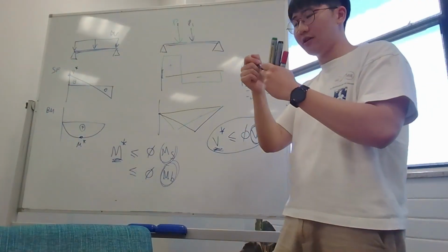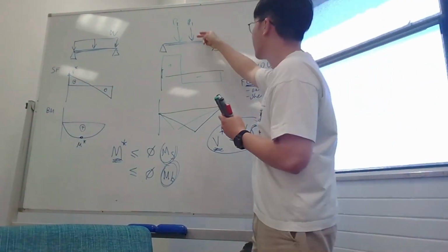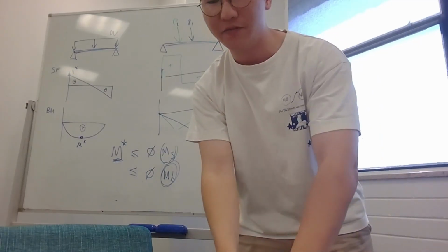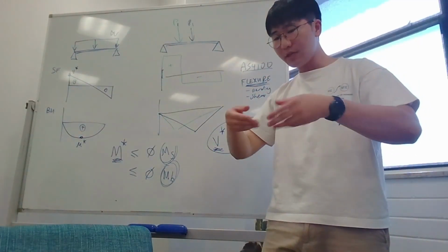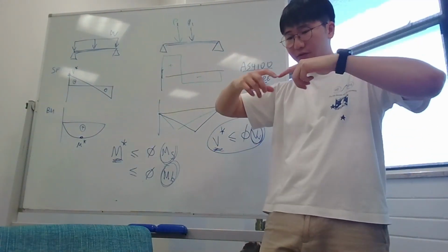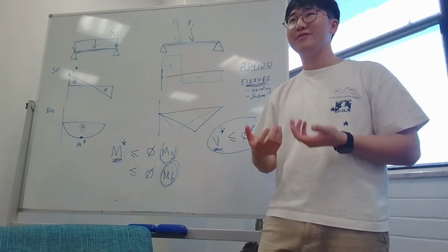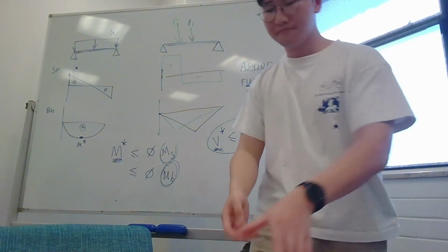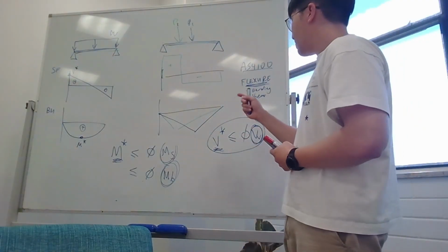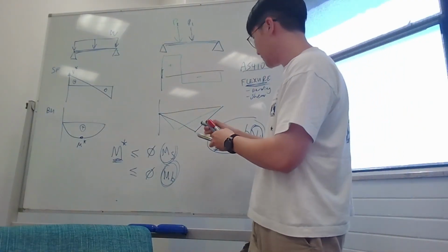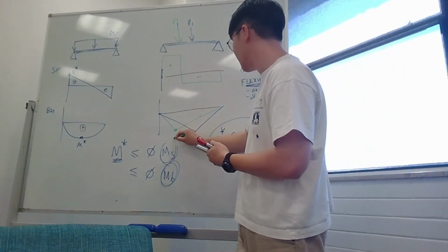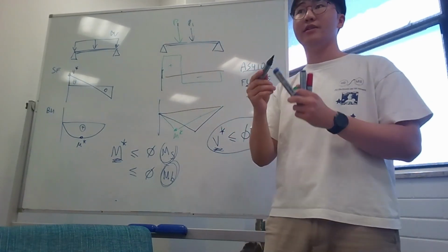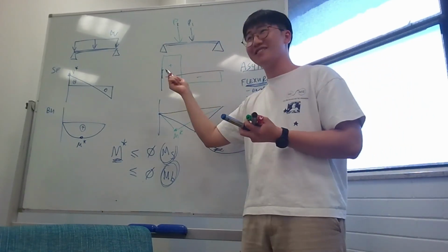So the worst case scenario for bending is if your point load is positioned right in the middle of your beam. Like you can imagine if you had a stick, and you put a transverse force right down the middle, it's going to break the easiest if you put the force on the middle, right? But you can see it actually dropped in terms of its moment when we've shifted P to the side. But the shear force has increased, right?